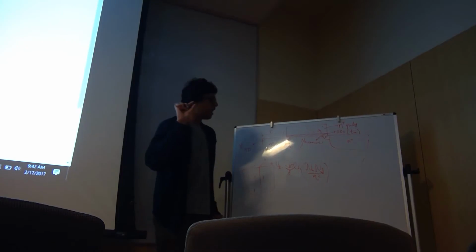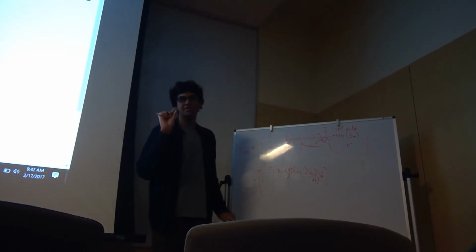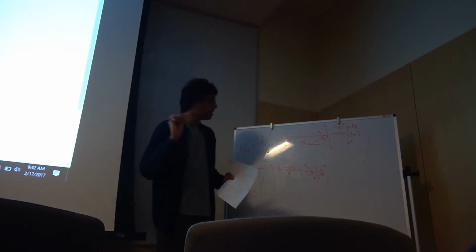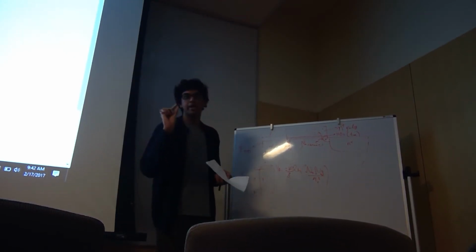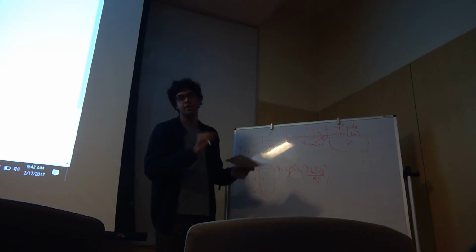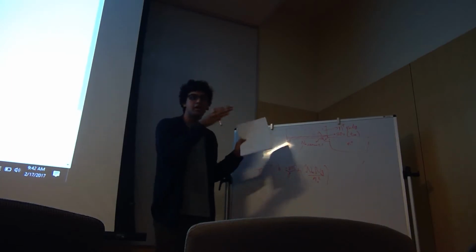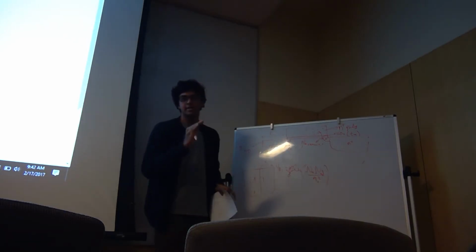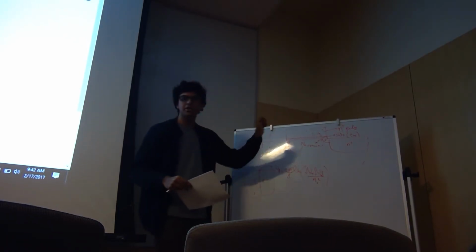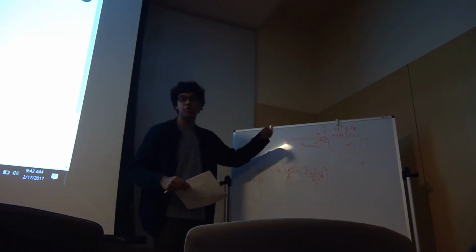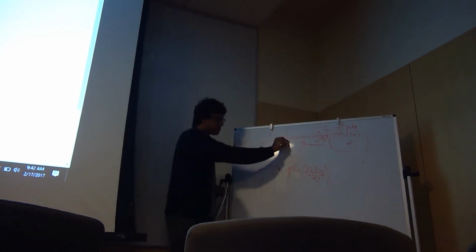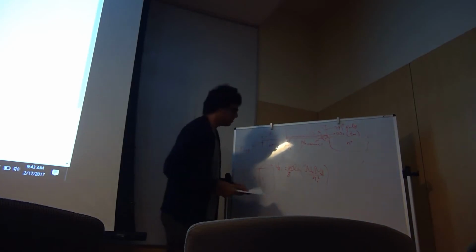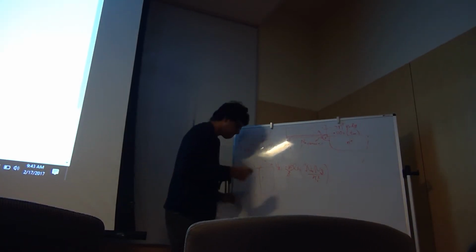Now, I would tell you to make it shallow because it's challenging to make it shallow from a process standpoint, so you need to know how to make it shallow. But from a device standpoint, by making it shallow, you can make the dependence of threshold voltage on the length of the transistor and on your applied voltage less. So by making this shallow, you actually make your threshold voltage more robust, okay? So you try to make this as shallow as possible, and you need to design this doping, as I'll tell you soon.